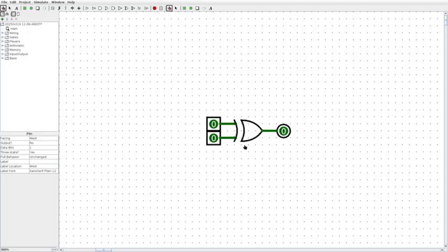Today we're going to learn about the XOR gate. The XOR gate is a basic computational device. It takes in two inputs and basically says if the two inputs are different, then the output will be 1. If they are the same, then the output will be 0. However, XOR differs from NAND and NOR in that it is not a universal computation.